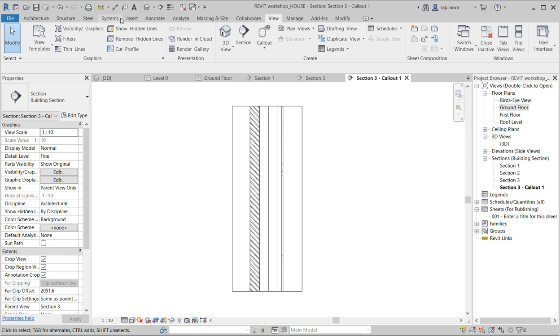Okay, to do this, you see this is almost like Photoshop on top of the drawings. You're actually adding another layer of information on top of the drawings. This information is not actually in the model itself. It's drawn on top of the model, in this particular view. So I usually liken that to photoshopping the CAD drawing. The things you do here are not replicated on other drawings. Because you draw the illustration here, it won't replicate on other drawings, and you've got to do all your details manually in different views, if that's what you want to do.